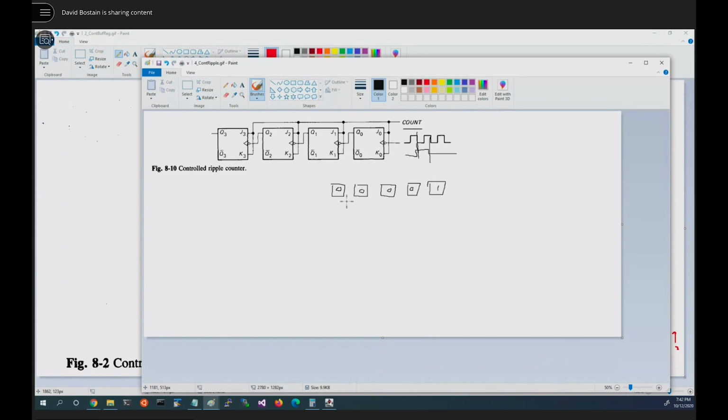Sadly, this can't do that. This instead counts in binary, which we might need. For example, in a program, we might need to know what the address of the next instruction is. And those typically are numbered in sequential binary order. But we wouldn't advance that every one of these 5 steps. We'd advance it once every maybe 5 clocks, because that's when the instruction changes, because it has to do 5 little sub-things. So we'll solve this problem in a second. All we need to have is a different type of counter.